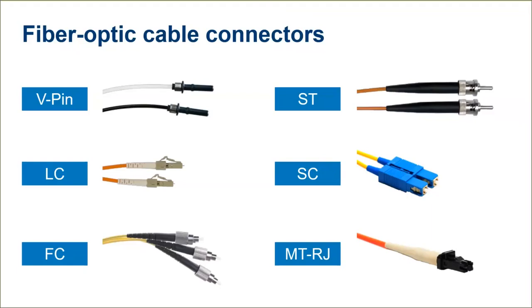Next below that is the Lucent connector, or LC, also known as little connectors. They are used in both multi-mode and single-mode applications. They provide latching connector retention in a very compact package. The LC connector is gaining in popularity due to its small size, and allows for very dense fiber installations. LC field termination kits are also available.